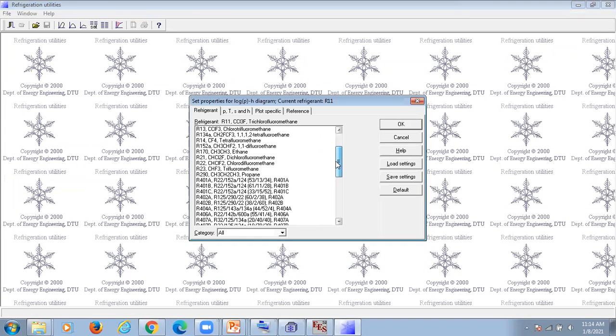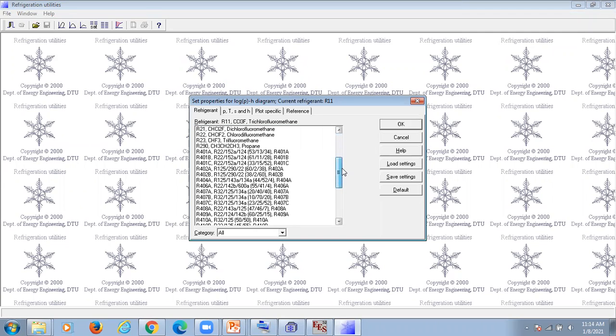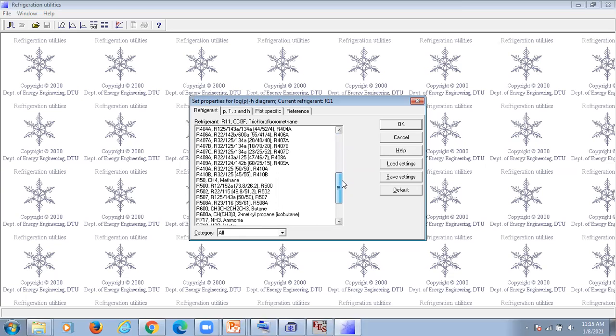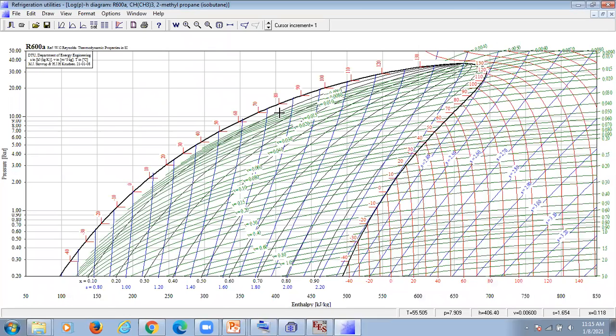Again, the pH diagram. And here you can see the list of refrigerants, all the primary refrigerants, and I'm considering the same for our case as previously discussed, the more eco-friendly hydrocarbon refrigerant. You may have some safety issues, but you have to take care of those. So the refrigerant we select is R600A. As I mentioned, you can find this even in your houses, but purity there is not that important. For a refrigerant, it should be perfectly pure, almost 100%. Almost 100% purity level is important for refrigerant.